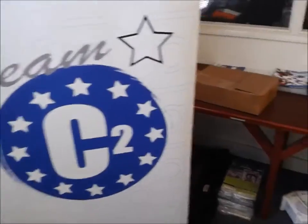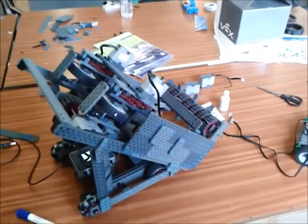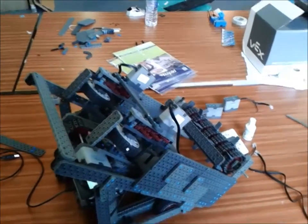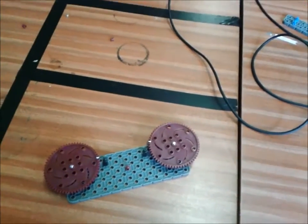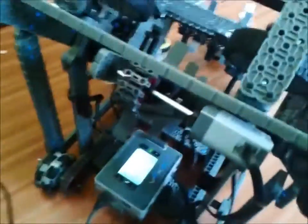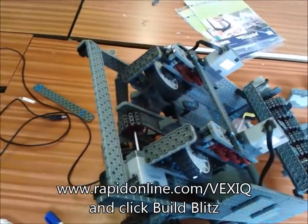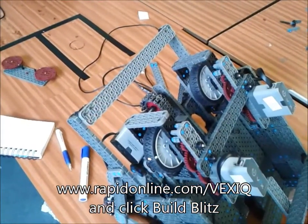Hopefully that gives you a bit of an insight into ways that you can measure your flywheel speed and look at the efficiencies of your gearboxes and your flywheels. The methods we used were the basic test bed to count the motor speed visually, the homemade stroboscope, and finally the Robot C code on the brain itself to get actual flywheel speed. So have a look at the resources on the site, and hopefully that will give you some pointers for flywheel design.